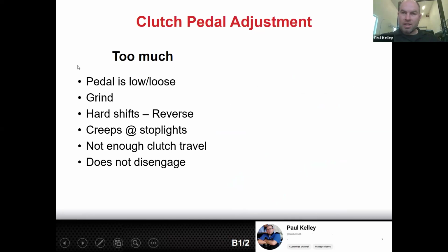That's like not disengaging the clutch all the way. So the diagnosis would be check the pedal adjustment. Well, the thing is, you didn't adjust the pedal. He didn't do anything with the pedal. The pedal adjustment's not really a thing. But that clutch isn't disengaging all the way. So he comes to the conclusion of, hey, this clutch is no good. This purple clutch is a piece of crap. You can't be having no purple clutch. But you could drive it.